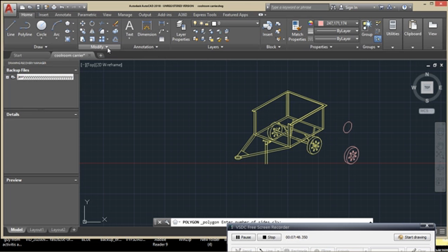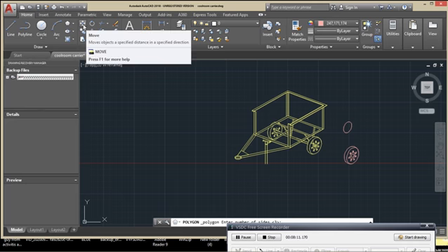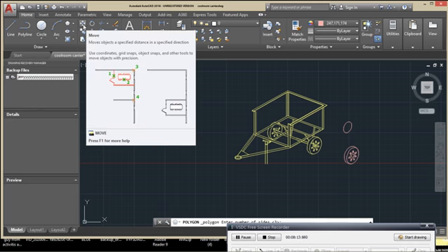You need to change something, you need to copy and paste. Instead of drawing the same thing again, you can just copy exactly what you've done and multiply it. That's what we mean by copy. Or after drawing a circle, you don't like the position at which you drew it, you want to adjust it a bit, you can click on the move. This is move. For shortcut, you just press M, enter. After clicking on the shape, you press M, enter.